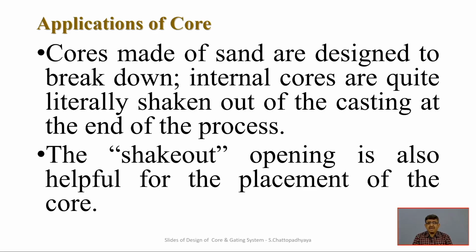Internal cores are quite literally shaken out, because after the casting there is one process called shaking, which is done on a vibratory screen where the casting is shaken violently so that any sand attached to it, from the external part or also the internal part in the form of core, comes out of the cast product. With the shaking activity it is easy to take out, easy to collapse and get the sand out of those hollow sections.